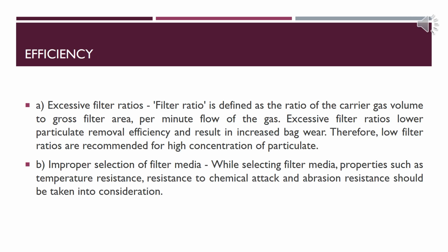The efficiency of a bag filter may decrease on account of the following factors. Excessive filter ratios. Filter ratio is defined as the ratio of the carrier gas volume to gross filter area per minute flow of the gas. Excessive filter ratios lower particulate removal efficiency and result in increased bag wear. Therefore, low filter ratios are recommended for high concentration of particulate.